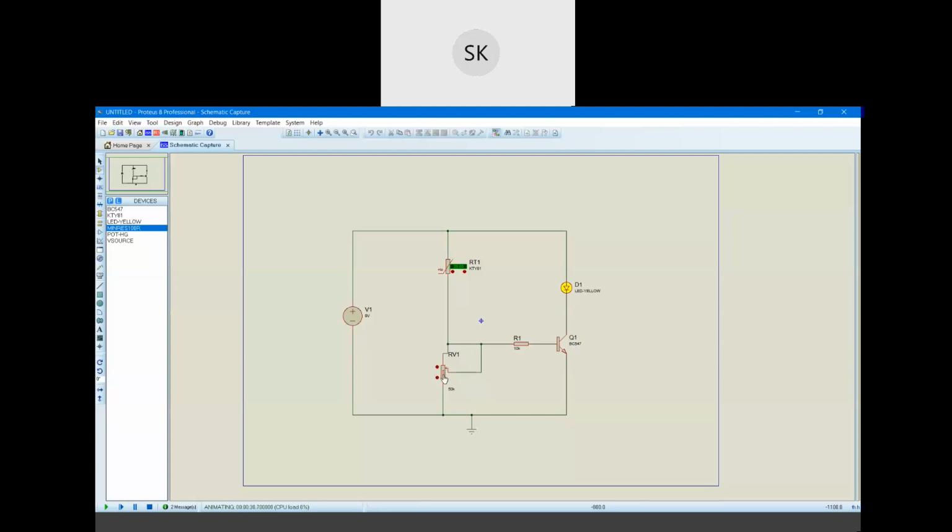We again need to add that potentiometer in the upper level and add that thermistor in the lower level, because R2 will be greater, and only then is the circuit going to work. Okay. Now we will proceed further.